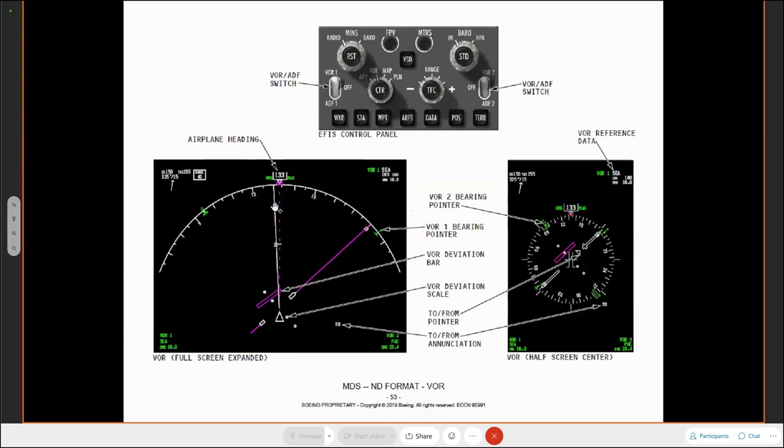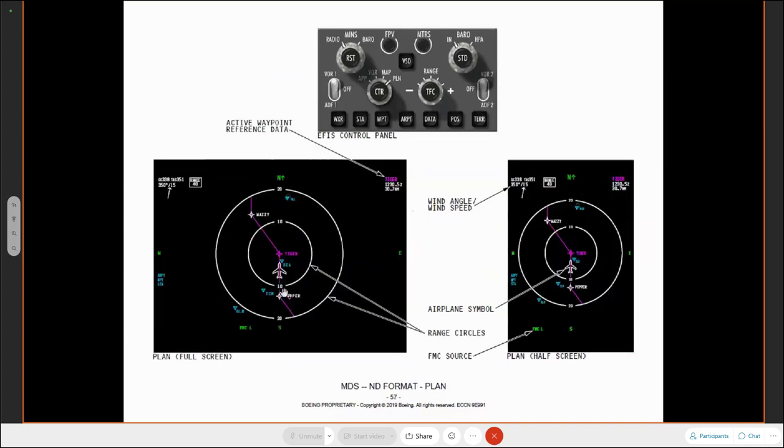On this display, 0 is in the center. I have 20 nautical miles in front and 20 nautical miles behind me. That's why it says 40 in that display here. The range itself is 40, what the display is showing. However, the halfway point is 0 in this case. And then you've got the other compass points, north, east, south and west.